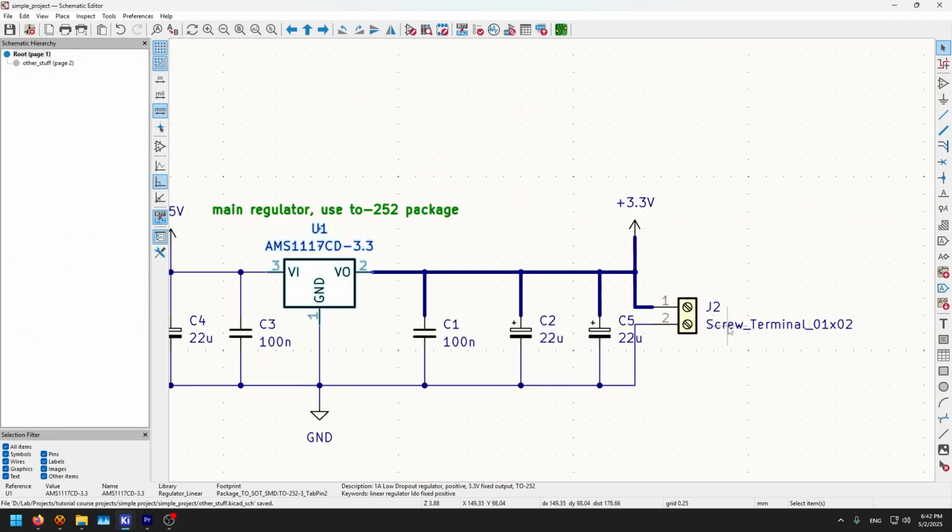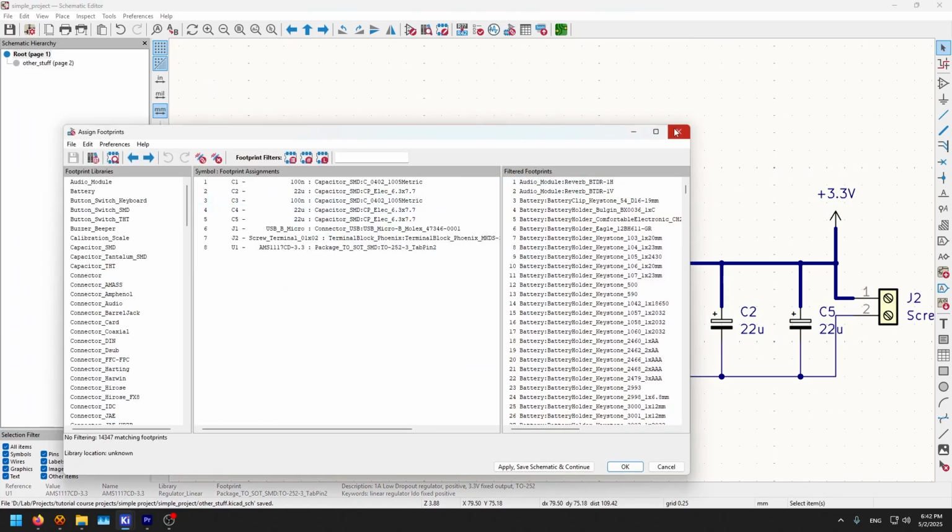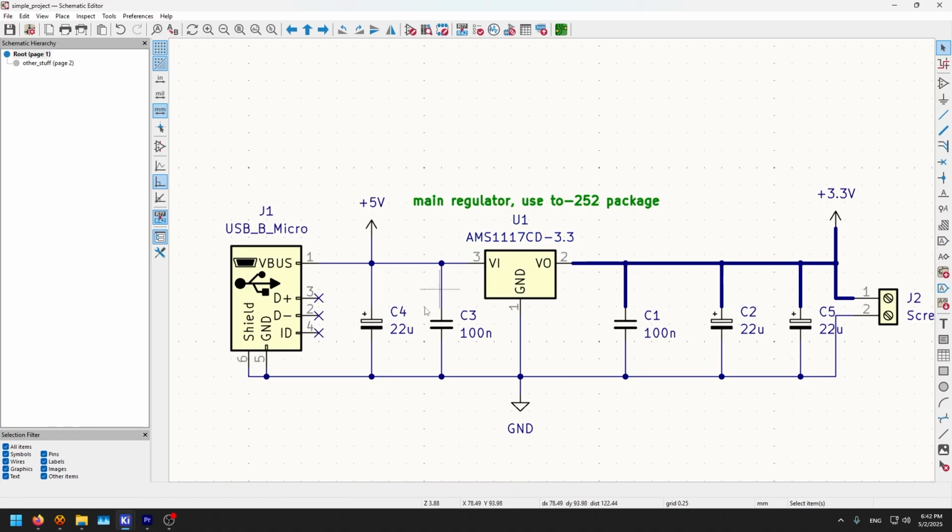and save, because the generic symbols like this one will not come with a footprint attached. Maybe something like a capacitor will not come with a footprint attached. So either you choose the footprint assignment tool right here to bulk assign them like we talked before, or you choose the method that I have shown you now, which is the manual mode, and this is more accurate, and you will remember everything that you have chosen, and so on. And maybe do a last check using the footprint assignment tool.